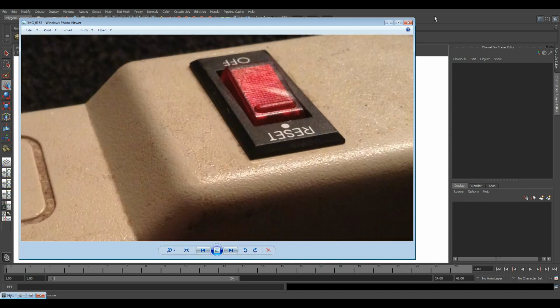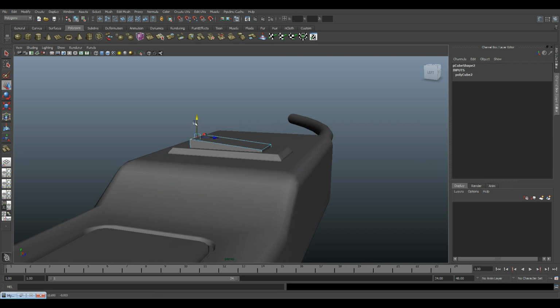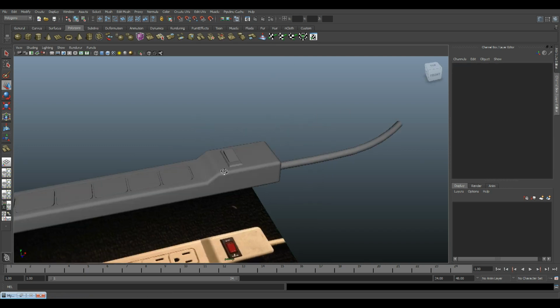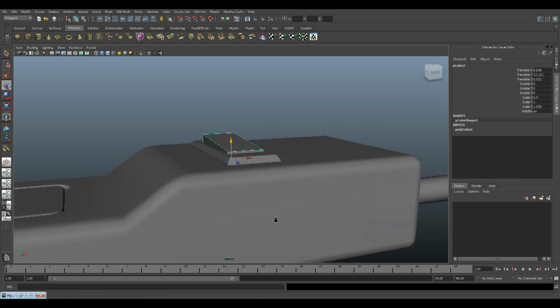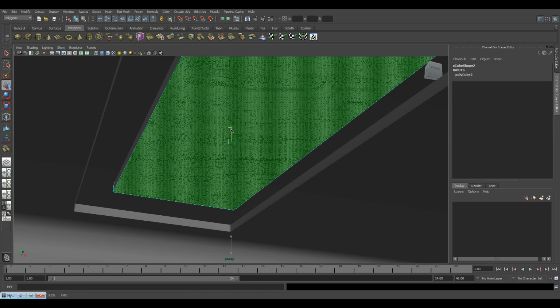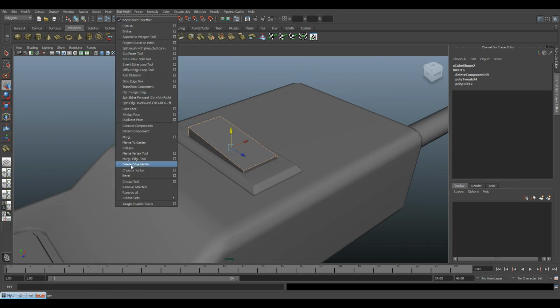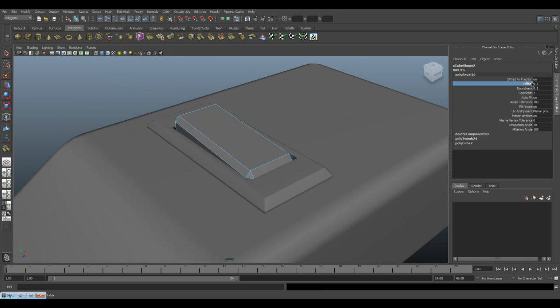okay. So take this edge here, bring it up a little bit more. And then I'm going to delete this bottom face here after I bring it up a little bit like that, and then delete it. I'm going to select all the edges on this, and I'm going to go Edit Mesh, Bevel, and I'm going to play with this offset here and make it about 0.3 with 2 segments.